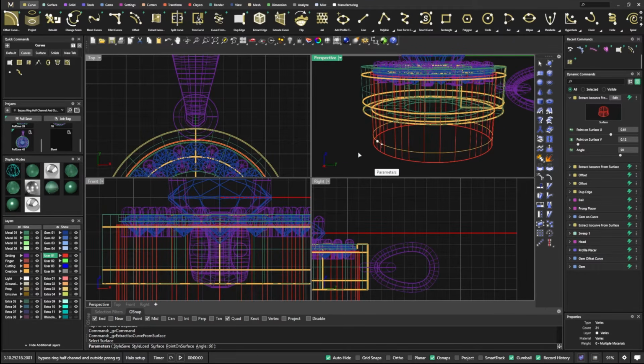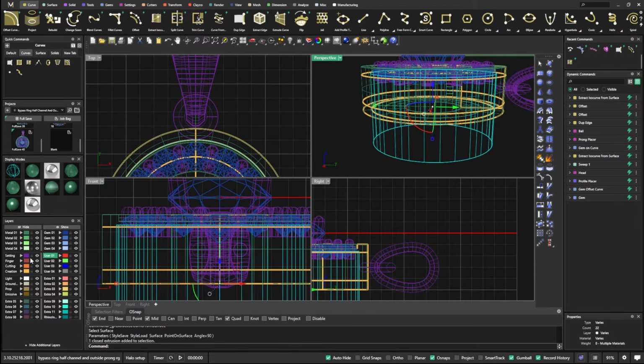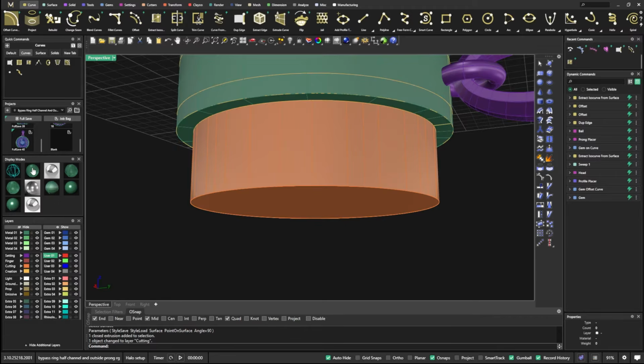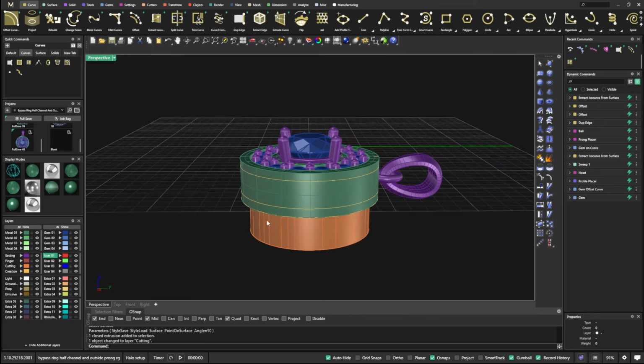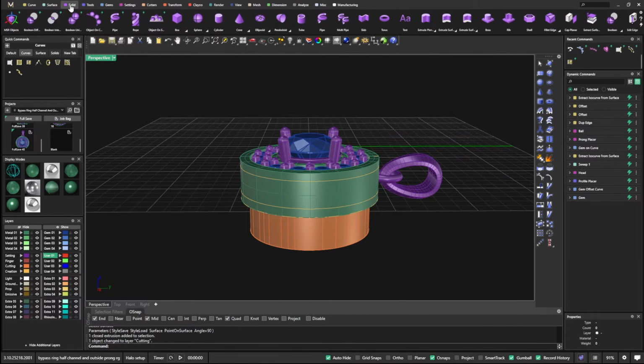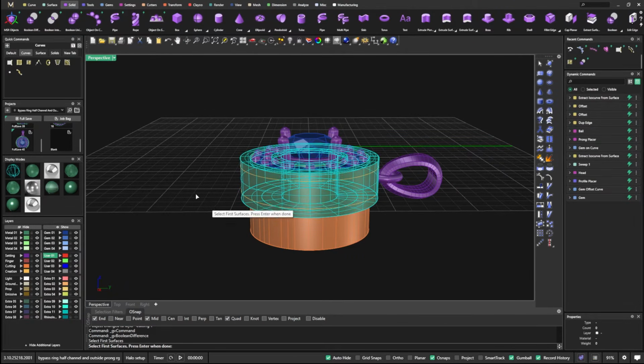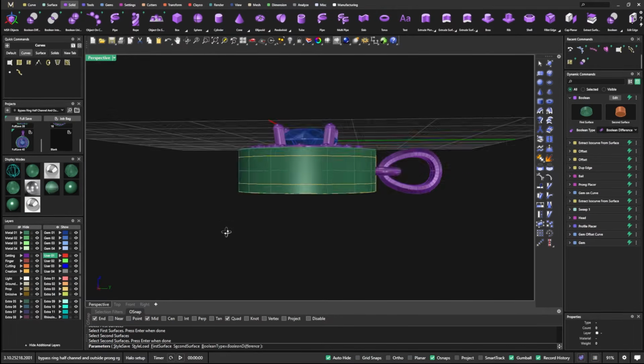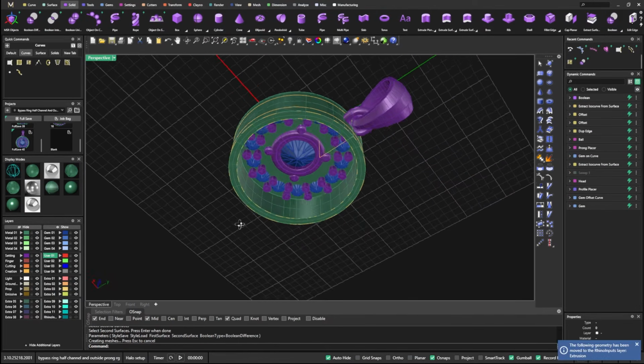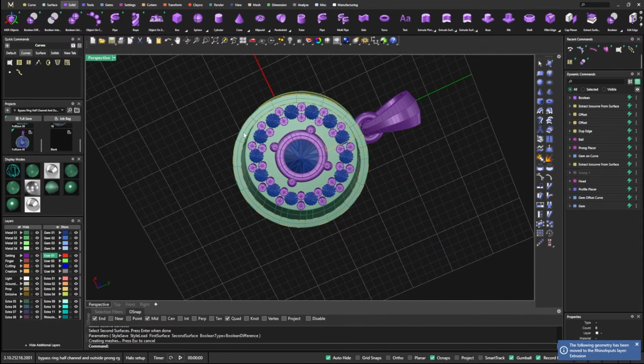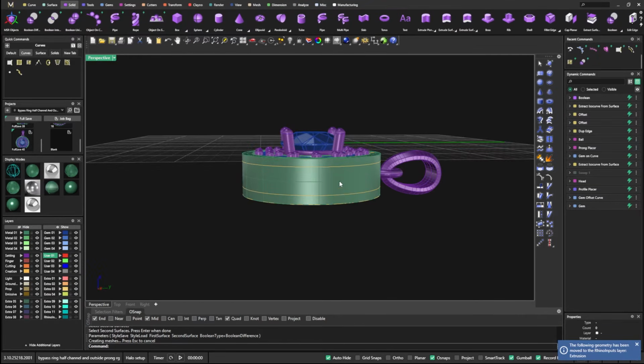So we have this here. We'll change that to a cutter, right? And we'll give it some shading, take a look at it, and we'll just go ahead and do this cut. So we'll go to solids, Boolean difference, right click, and now we have that cutout, right? With a 1.8 thickness, and now we're going to do this cutout.